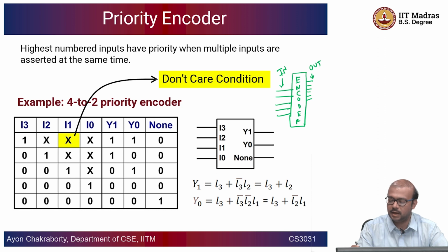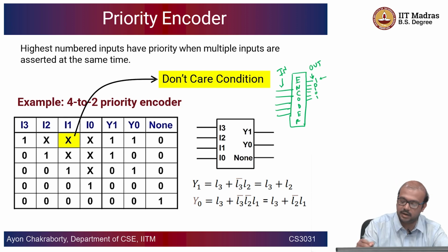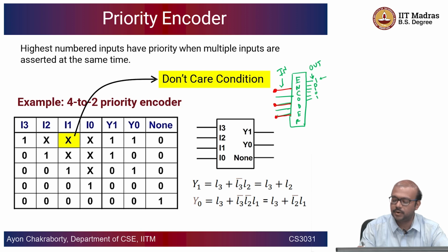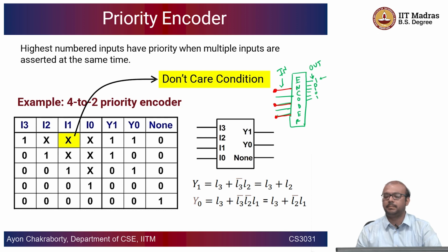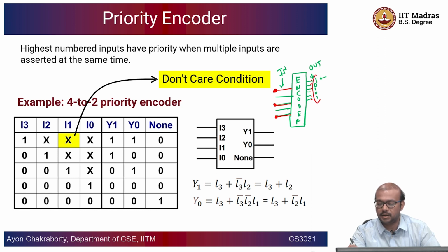Suppose you are encoding 1 0 1 0 1, right. So, this is going to correspond to something very specific, let us say this is your most significant bit, right. So, then it makes 16 plus 5, 21. So, probably the 21st input is going to be entertained, right. This means that somebody has inputted 21, but suppose you want to choose multiple ones, or more than one. Say this is activated, this is activated, and also this is activated. What should you do? You cannot output 3 different bit patterns, right? Because if this is 6 bits, or 5, whatever number of bits, whatever bit pattern you are generating corresponds to only a single line here, right.